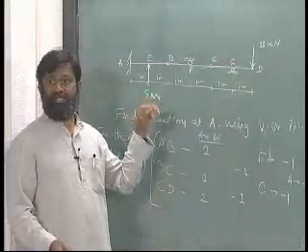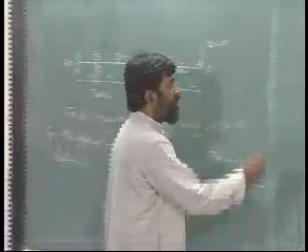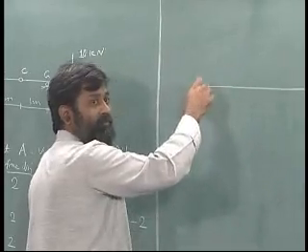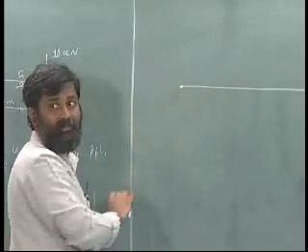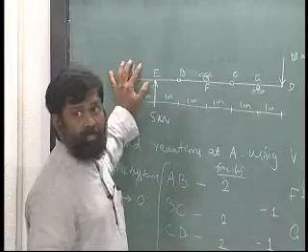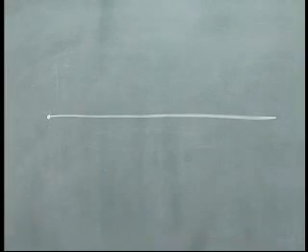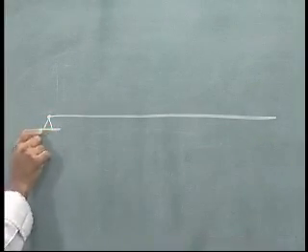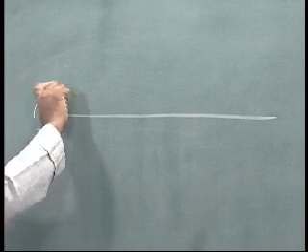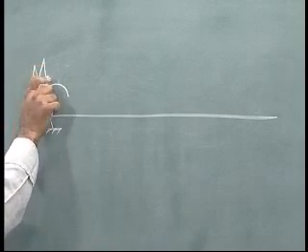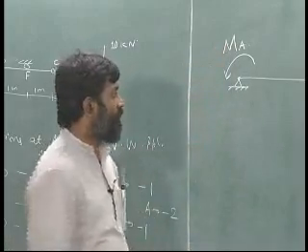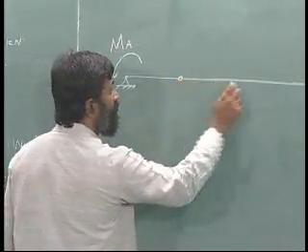I have to release the rotational degree of freedom at A, which means it should be possible for it to rotate about this particular point A. If I have to allow only rotation, it is very simple, all I have to do is convert it to a hinge and apply a moment. We need to find out this moment A.